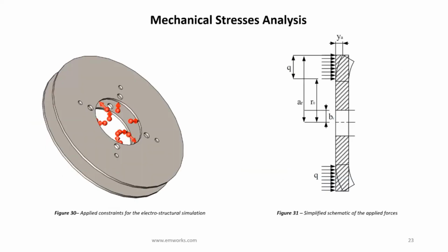Before coming to the end of this presentation, we have dedicated this section to talk about magnetic axial flux forces that can be generated in axial flux machines. These forces are very high and can produce important mechanical stresses in the ferromagnetic parts. EMS, coupled to a structural solver, can help to predict the mechanical deformation caused in the structure of the rotor cores. Figure 31 shows the force density applied in the rotor cores of the studied machine.